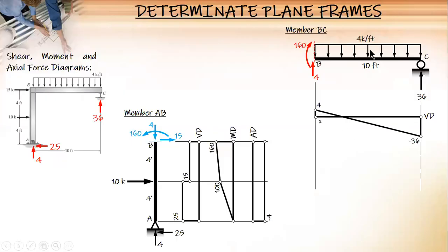My technique, 4 divided by 4, it's 1. And then, the moment diagram, we already have 160, no? It is 160. And then you add the area, one half of 1 times 4, it's 2. Plus 160, so you have 162, no? Remember the curvature is concave upward, but downward, no? But since the area is positive, you mirror it, so it is concave downward, going up. 162.